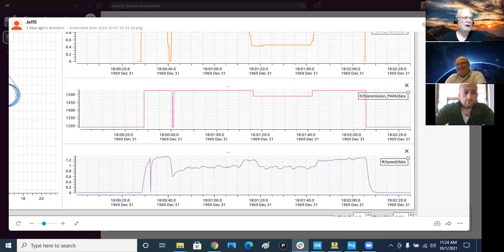You can't put it up on a jack because, I assume this slash speed is your value from GPS. Yes. I asked that on one of the posts, you didn't respond, but later you put up a graph saying, okay, now we're going to add in the speed from GPS, and you had it marked speed. So I was digging through the Google Drive, and I think I found where you were subscribing to the GPRMC message, pulling off the ground speed and publishing that. Yes, that's ground speed. Because when I went through the trouble to take the slash vel message from the driver and break the speed out of that, it was matching your speed.